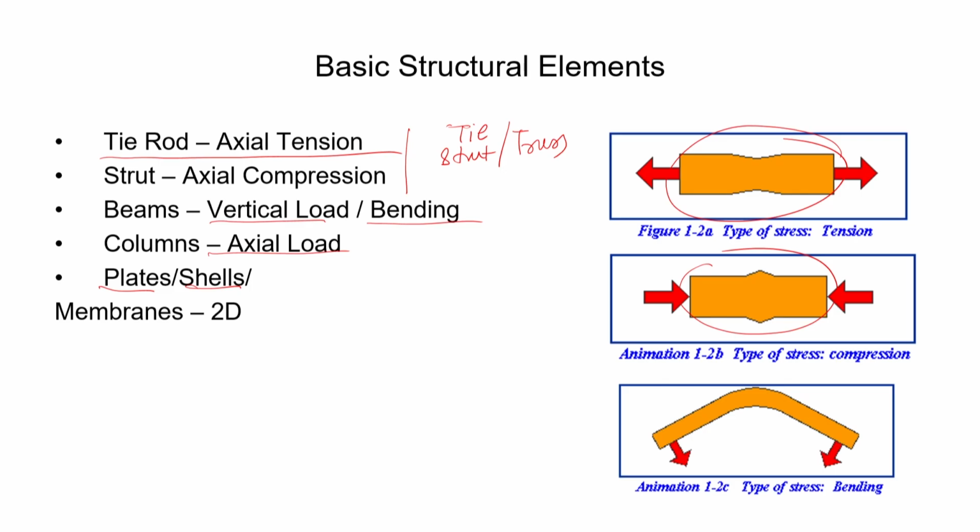And in the form of shells, even thinner shells can still carry some bending moment, but membranes cannot. Membranes can only carry the distributed tensile forces. So, these plates, shells, membranes, etc., or so to say the thin shell structures, you can call them thin shells. So, shells are thick shells and thin shells. So, all these things together, they are the basic structural elements that you can consider for a particular type of product. Now, how am I going to arrange them? That of course involves a particular team-specific work.